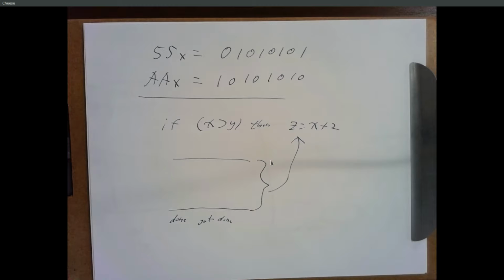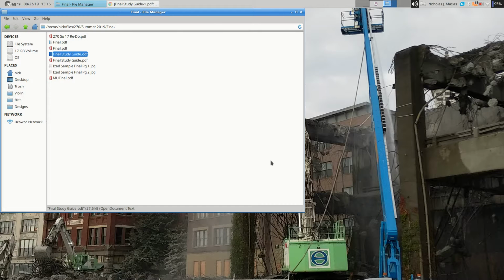You'll have a question that uses indirect registers, similar to the homework that you just got back. So dealing with FSR 0, 1, or 2, high and low, and dealing with INDF 0, 1, or 2, or POSTINC or PREDEC or whatever you choose. What else? That's what comes to mind right now.